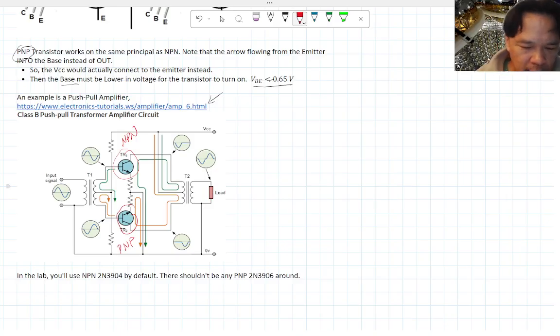And what happens is that you have a signal that's an AC voltage. Okay, so when the voltage is positive, it flows through the top transistor. And then you're basically pulling current through the collector into ground here, and then you're actually able to drive whatever device you're trying to drive, the load.